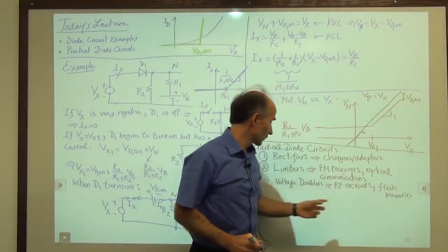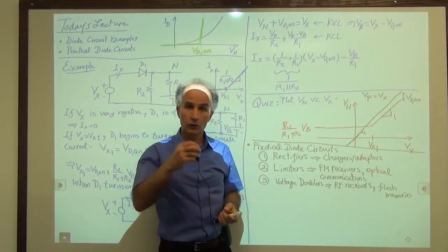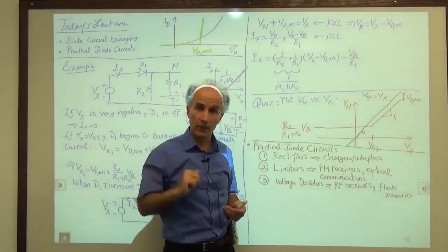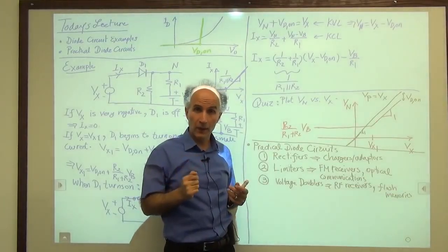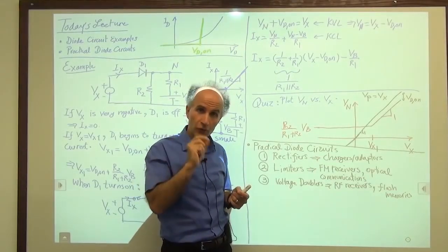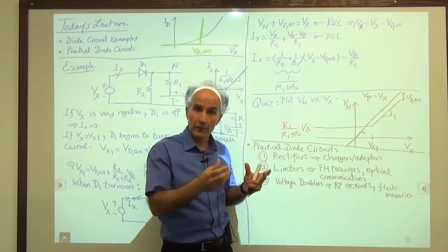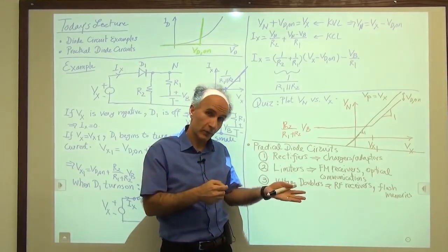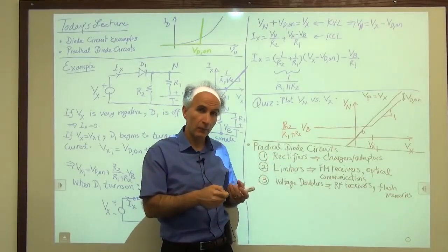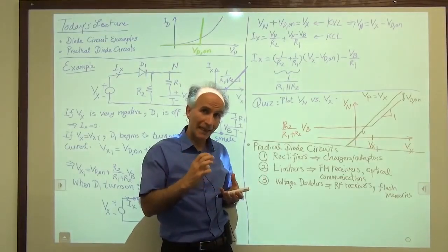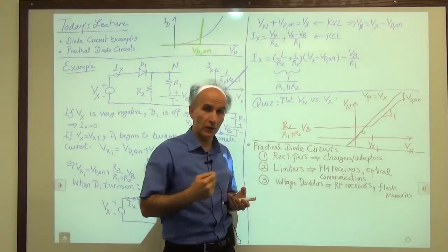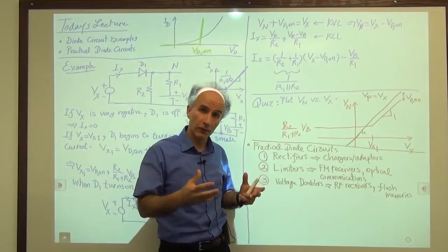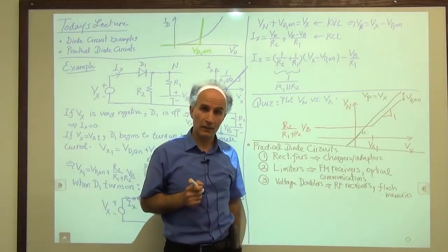Why does that flash memory need a voltage doubler? Well, in order to write information onto the memory, sometimes we need a high voltage in the memory. And that high voltage is not available. For example, if you plug in the flash drive into your laptop or into some other portable device, the voltage that that portable device has may not suffice for the voltage that the flash memory needs in order to write information into its cells. So it generates its own voltage inside, a higher voltage, using circuits such as voltage doublers.